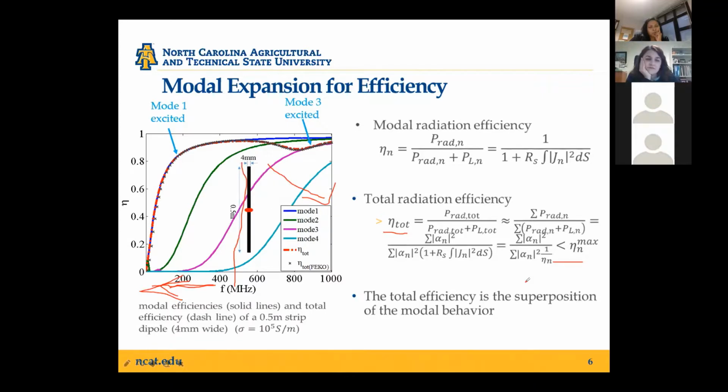I see your point. So in the physical world, when you excite an antenna, the efficiency you see will be a combination of different modes, and so I think in that case, your best efficiency is definitely around the location where your mode is resonant. In the model efficiency I plotted here, we didn't consider any physical excitation. So we are assuming each mode is perfectly excited. So that's why you see a pretty high efficiency as the frequency increases.